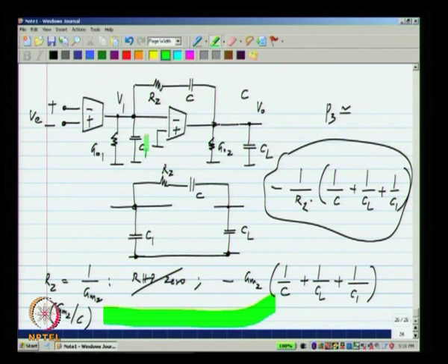And in the extreme case, when let us say RC is infinity, then you will not have this capacitor here at all. You will have these poles very close to each other. Earlier we saw that when this branch was not there, when C was not there, there was some pole frequency here and something else there, and when you introduce C, they moved further apart, which is good for stability. Now, if you make RC equal to infinity, that is very large, then you will go to the original case where the poles are relatively close to each other, which is very bad for stability.